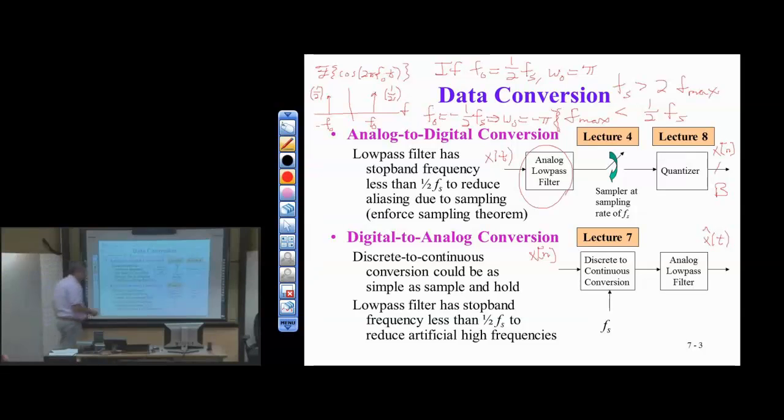All right, so here we're going to try to reconstruct, and the sampling theorem tells us it's at least possible. It tells us that we can reconstruct frequencies up to half the sampling rate. Remember, the sampling theorem assumed that there was no frequency content above f max, which is an idealism and not going to hold in practice. But what we can take out of the sampling theorem as far as practice is concerned is that when we do this reconstruction, when we do digital analog conversion, we have the hope that we can reconstruct frequencies from 0 to half the sampling rate.